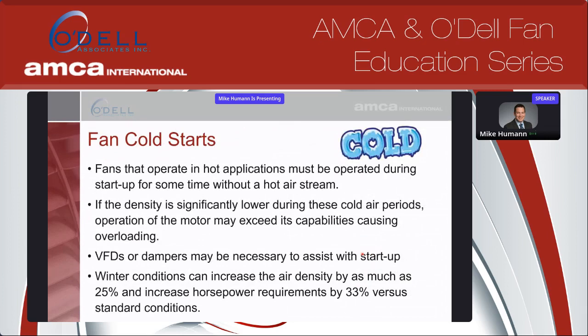Also, when it's cold out, or if you have a hot application at ambient temperatures, there are some considerations to take into account when you're starting up that fan. If the density is significantly lower during these cold periods, you need to make sure the motor can handle it. Ways of dealing with that are to put it on a VFD or even a damper to choke back that fan while it's going through startup.